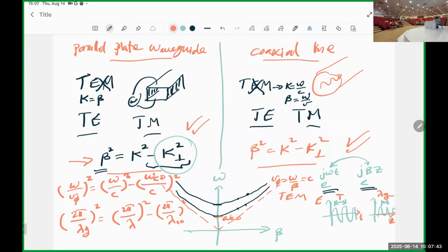In a smooth wall waveguide, for the first mode, we have this. This is the stop band. And the pass band is going to be any frequency above that. But close to omega_co, which is the cutoff frequency, the slope here is really zero, right? You have a zero slope. The slope in this case is basically the group velocity.